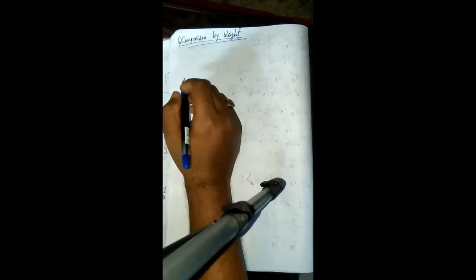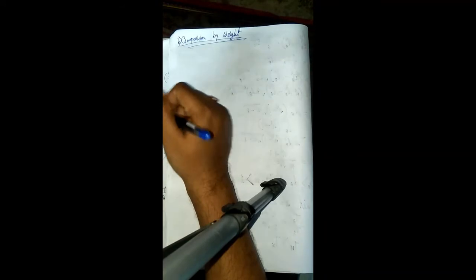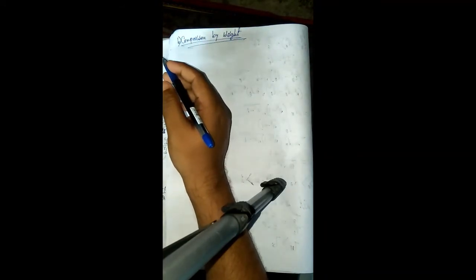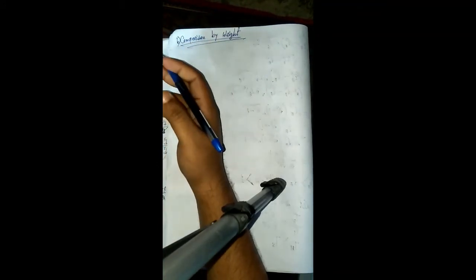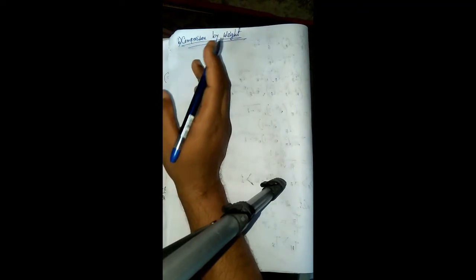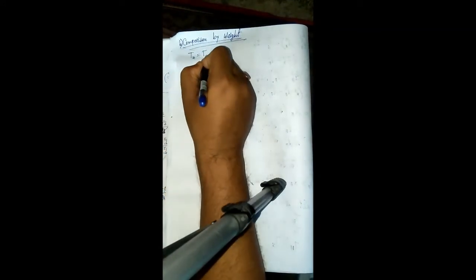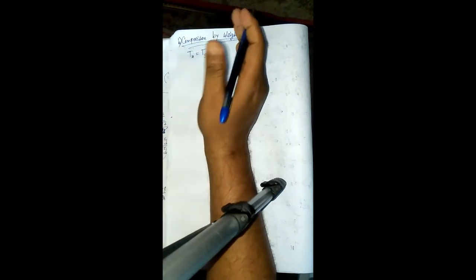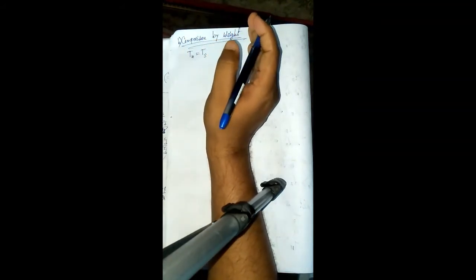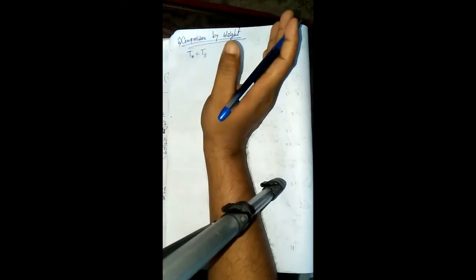Thank you. Students, after comparing the solid and hollow shaft by strength, let's compare the hollow and solid shaft by weight. In this case, it is assumed that both shafts have the same length and material. Now, if the torque applied to both shafts is the same, that means TH is equal to TS, then the maximum shear stress will also be the same in both cases.